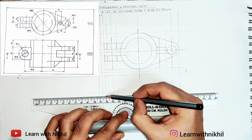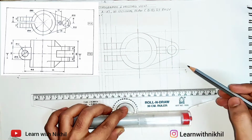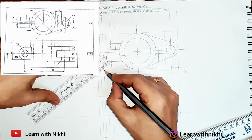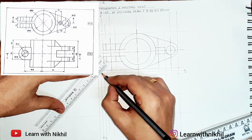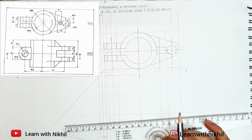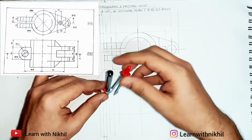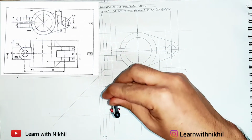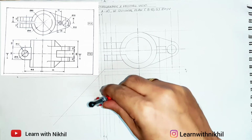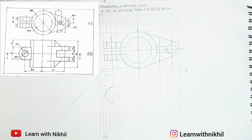Now in the question there is an error. The outer semicircle radius given is 12 millimeter, but the thickness of its diameter given is 30. So there is an error over there. So you can either take the diameter as 30 and radius as 15, or you can take radius as 12 and diameter as 24. So I am taking radius as 12 because in the front view we have taken the radius as 12 at the start. So this is the semicircle with radius 12.